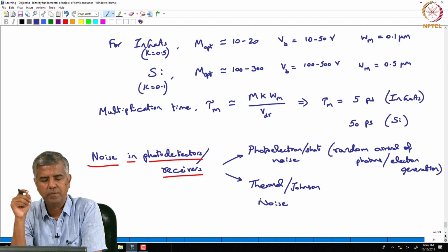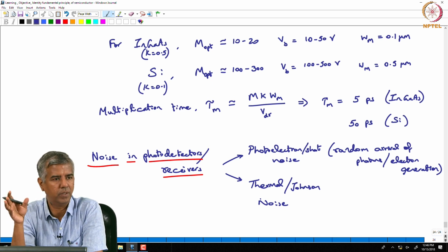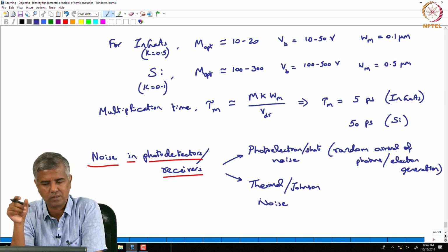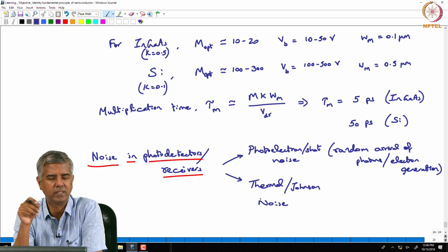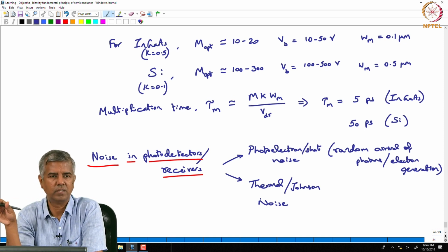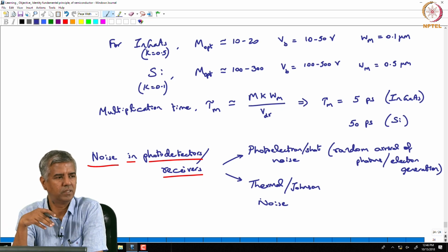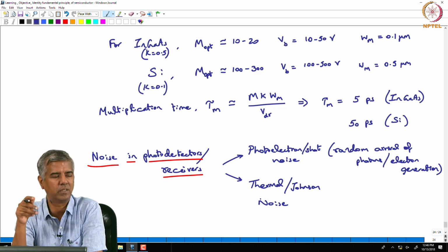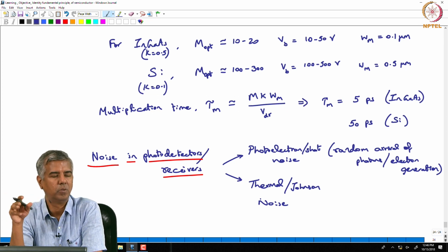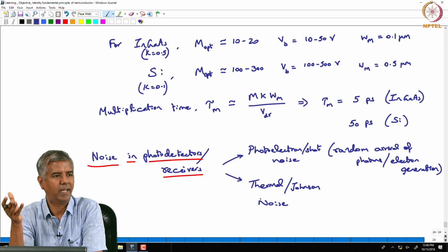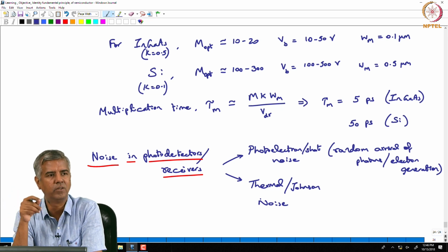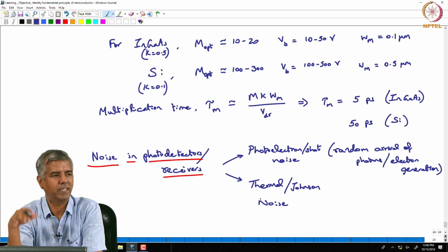Thermal noise happens when you send a photocurrent through a resistor, for example. That resistor has a particular value, and on the average it allows this much current to pass through, or a certain rate of electrons going through, but that rate actually depends on the number of collisions that it has while propagating through, and that is a random process by itself.